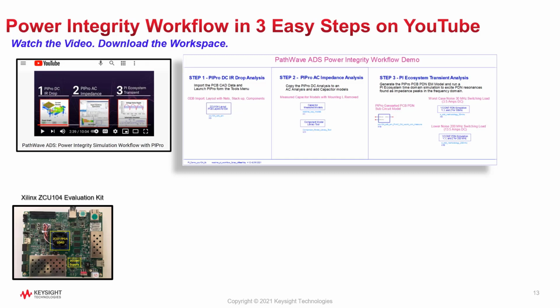This DC-AC time domain workflow highlights the importance of using EM simulation to get the PCB parasitics correct and using measured models to ensure accurate ESR and ESL parasitics for the capacitors and behavioral models for the VRM.